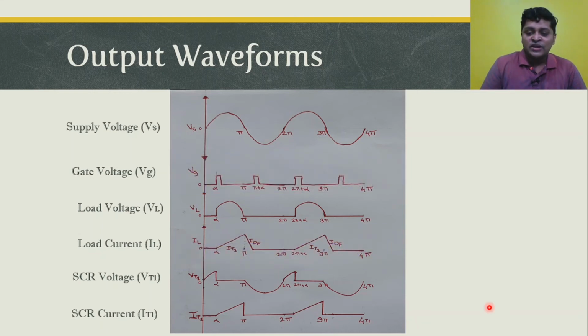Now we are interested in calculating the DC voltage across the load, and again DC is nothing but the average. So keep in mind, what is the effect of the freewheeling diode? The freewheeling diode minimizes the inductive effect of the load, and because of that, it restores the load voltage condition. And this is the key thing we like to take from the working of this particular circuit.